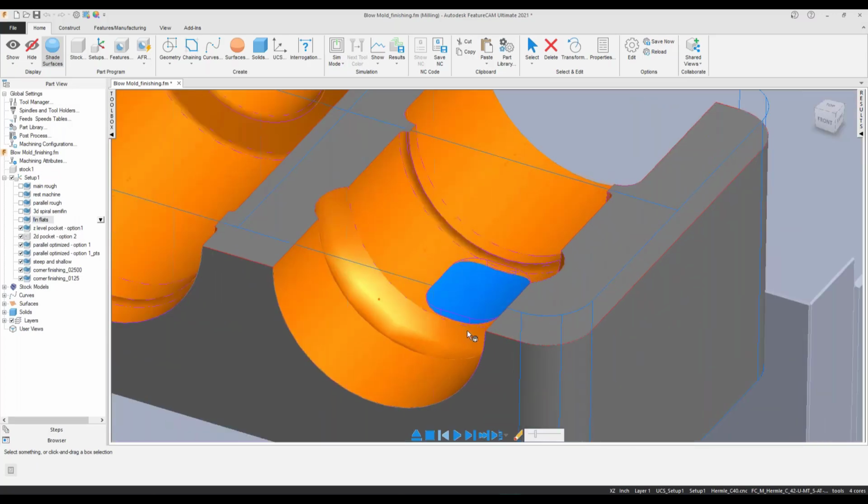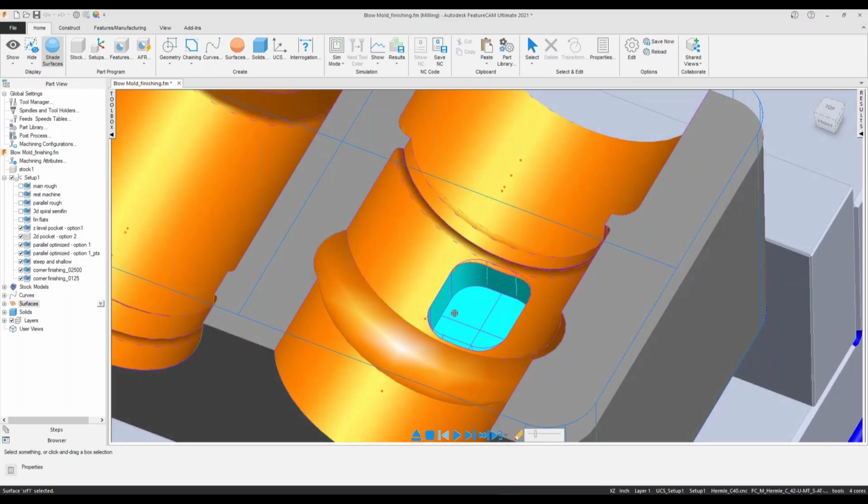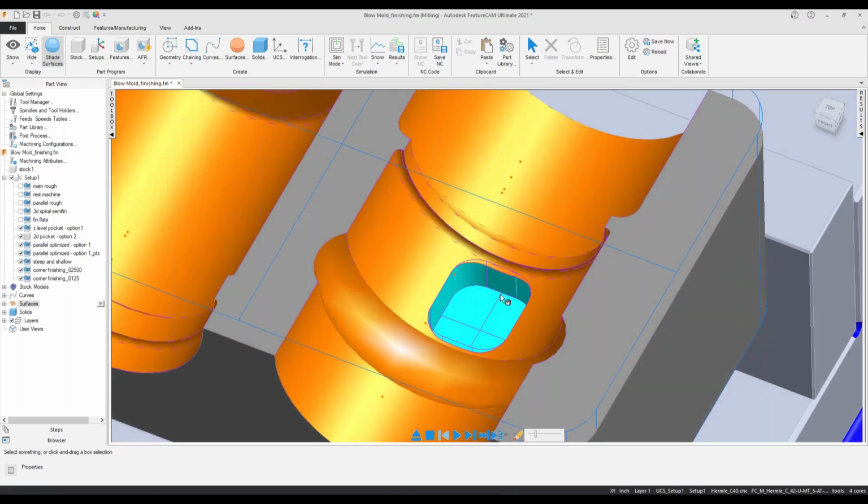What I wanted to talk about is this pocket down here. If I just select this surface and do a Control J to blank that surface, let's look at this pocket. This is where it's nice to have a mixture of 2.5D toolpath and a 3D type toolpath, because I have the choice. You can see here I've got 2 different strategies that attack this region. Let's go ahead and look at each option here.